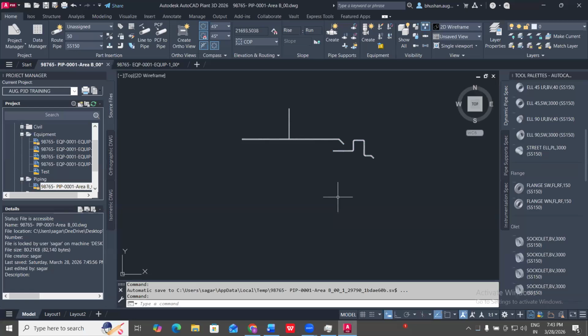But with the elevation snap turned on, it will snap to the exact point on the vertical pipe that matches your current elevation, right? So to turn on elevation snap during routing, you can right click and find the elevation snap ribbon option, or look in the compass panel on the ribbon. It toggles. Click to turn on. Click again to turn off.